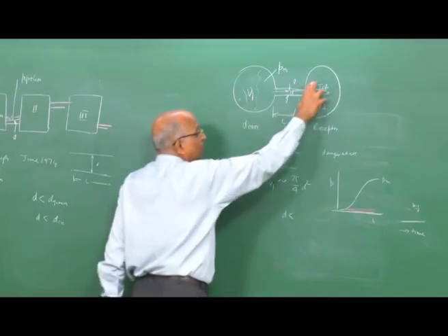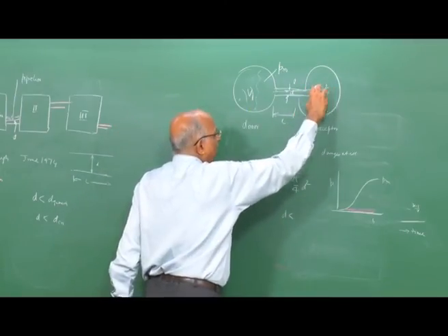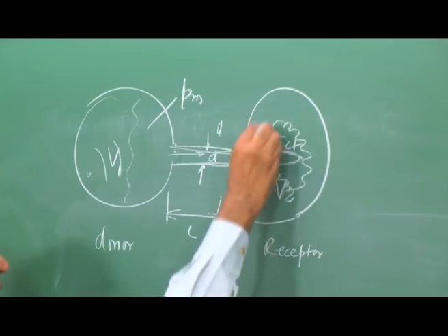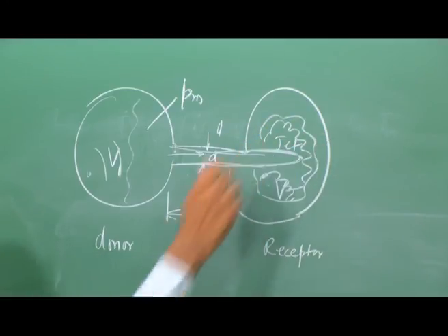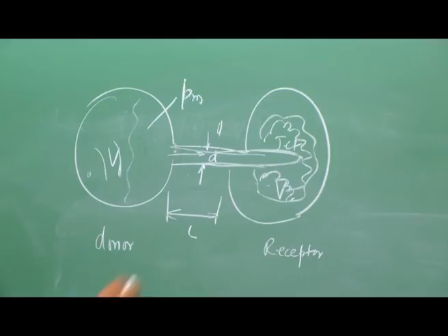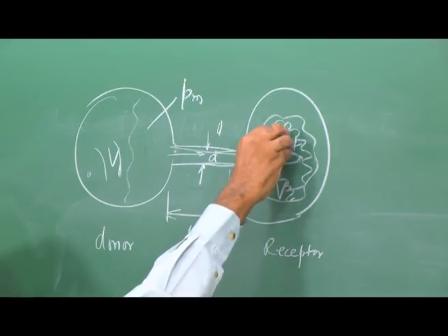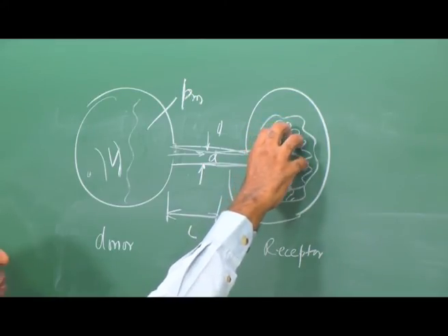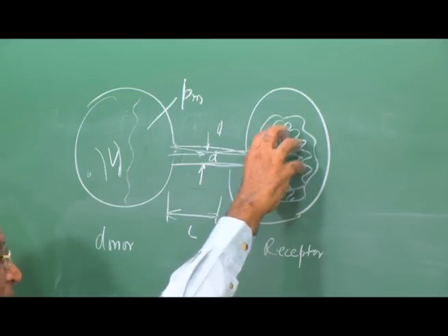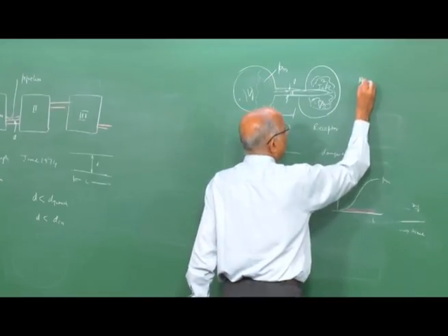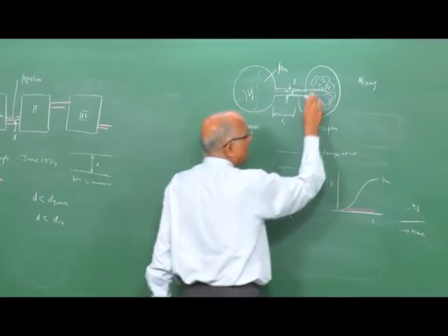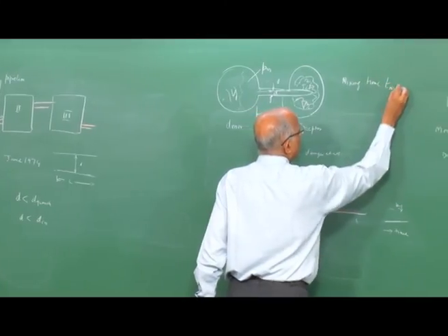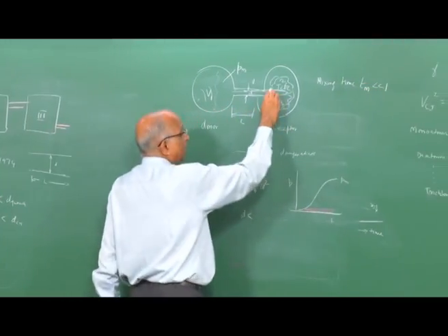If this hot jet comes into this particular reactor over here, and if this hot jet immediately mixes with the cold reactive gas over here, or with the gases in this particular volume, what is going to happen? Well, this jet gets extinguished, and therefore it is not possible for you to initiate combustion over here. And if the mixing of the jet with the gases here is very rapid, that means the mixing time, let's say Tm, is a very small number, well, I cannot ignite these gases